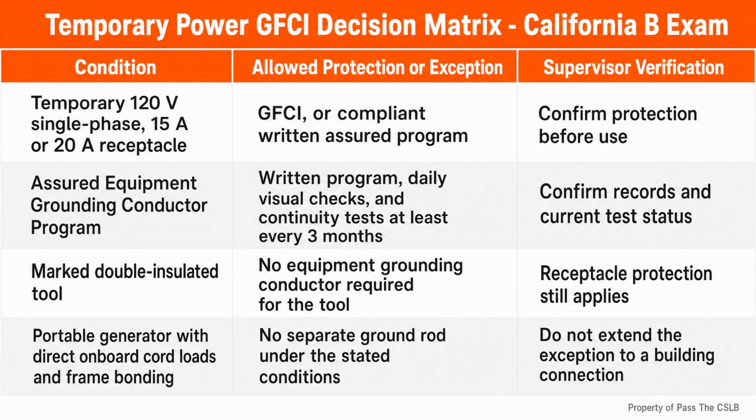For general building supervision, the practical move is not to calculate conductor size. It is to notice exposed metal, wet conditions, reach zones, missing bonding connections, damaged grounding pins, and work that is about to be covered. Then I bring the electrical contractor and the inspection authority into the issue before the defect disappears behind finishes.